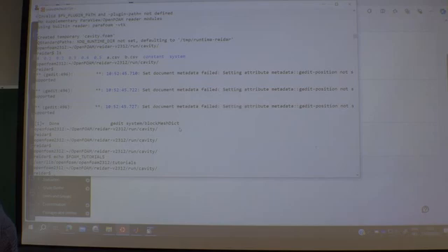Yeah, should be under user lib on my computer. So if I now search for user lib, and then we had OpenFOAM, I can search the entire OpenFOAM structure, not just the tutorial, but everything. And I want to find a file, type F, with the name sample dict.